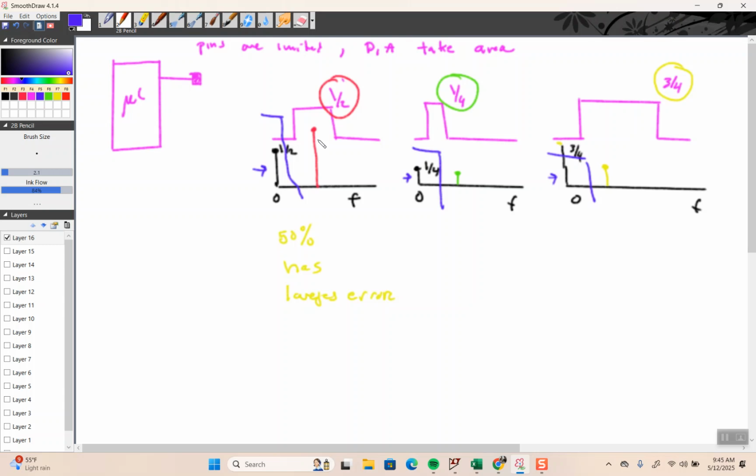With normal digital to analog converters, you have to check every code, right? So if I had a 4-bit digital to analog converter, I have to check this, and then I get 0. Then I have to check this, and then I get the least significant bit.